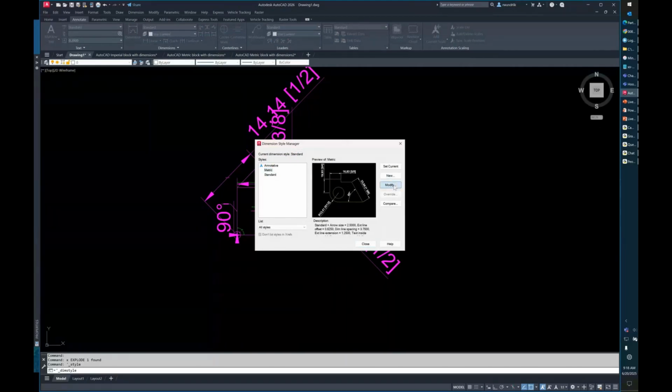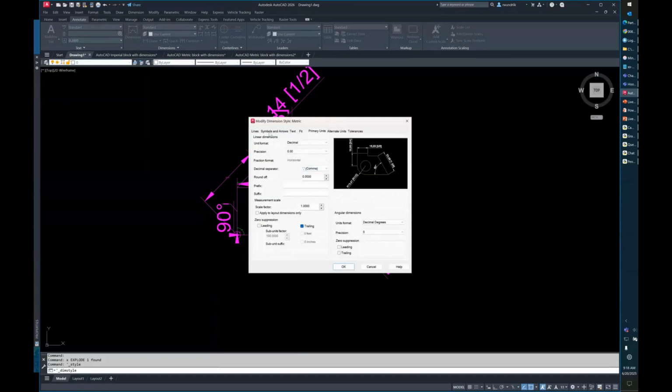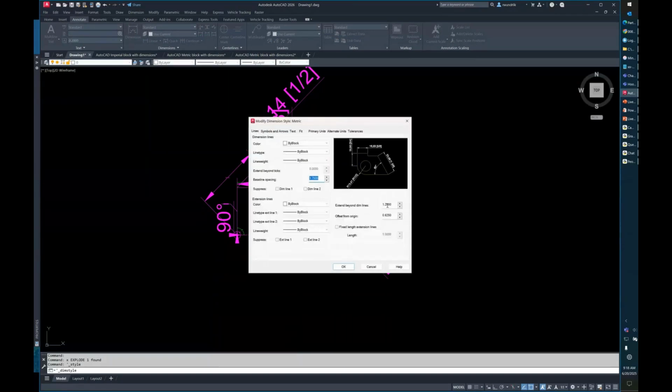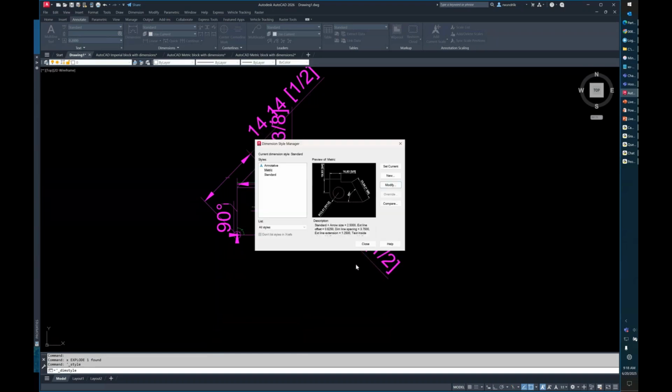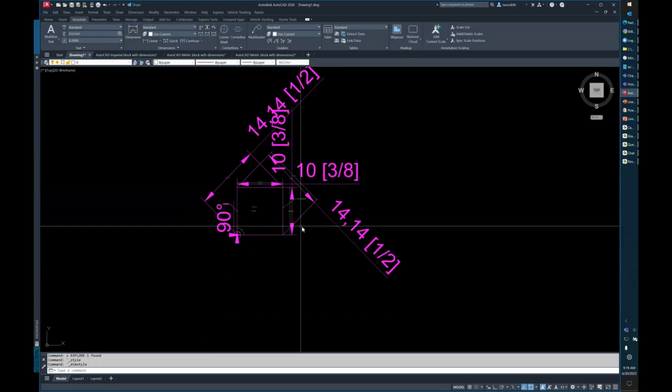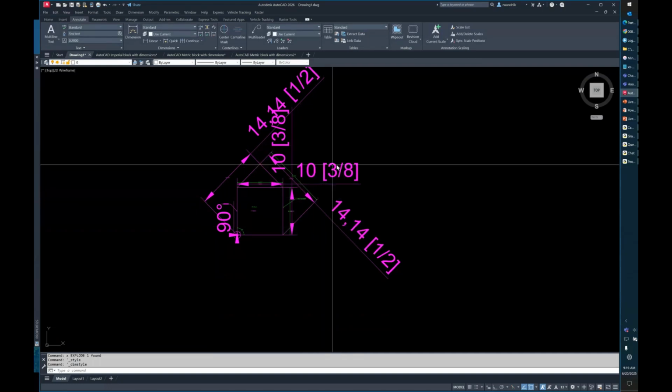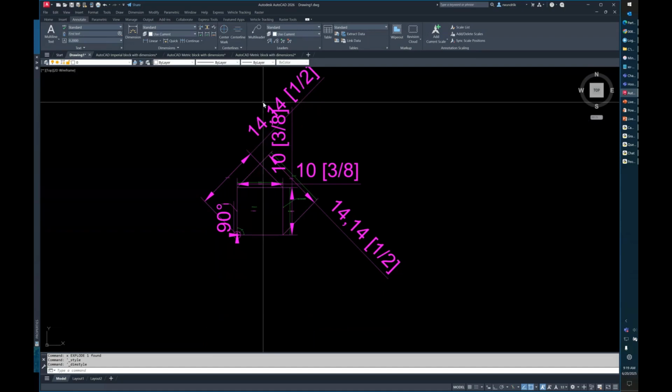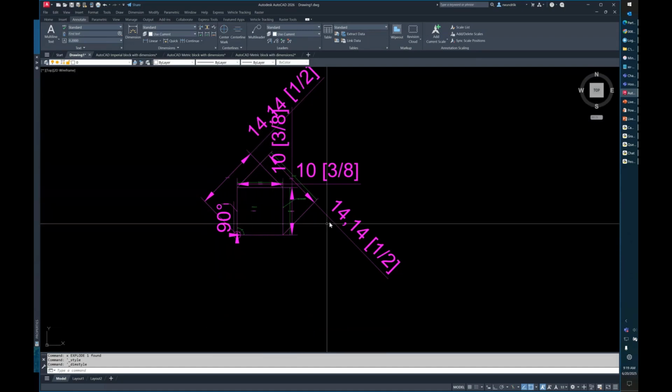And when I go to modify this, you're going to see that it brought all of these pieces in exactly as they were done in the drawing. So it did no conversion when I exploded this. It just simply brought this in, and now this is 3.75 inches instead of 3.75 millimeters. That's the pitfall. That's why things don't come in right. That's why things go badly when you explode a block that's incorrectly unitized, for lack of a better term. Those are the things that cause the problems.